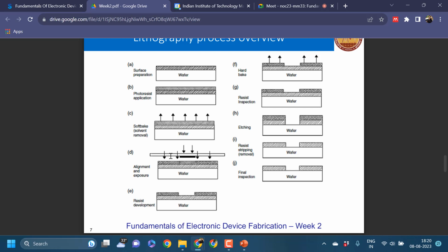The process of transferring the pattern onto the substrate wafer. Yeah. So lithography is the process of transferring the pattern onto the semiconductor substrate. It is the most important step in miniaturization, and newer patterning methods are being developed so that smaller and smaller circuits can be transferred onto the substrate. Using lithography we can create a pattern with specified dimensions, and we also adjust the placement of the pattern with respect to the base crystal orientation so that maximum efficiency can be achieved.